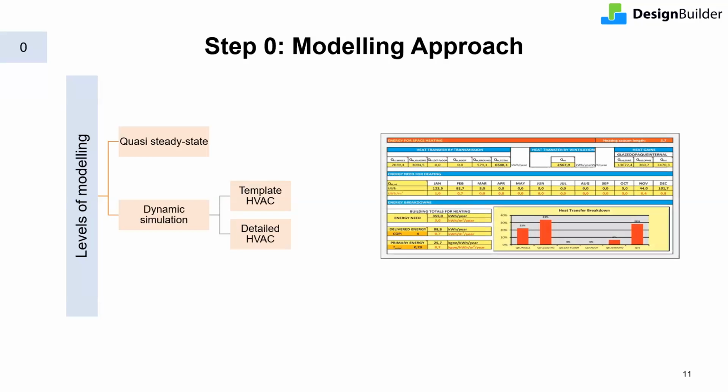Steady state modeling, such as using spreadsheets or PHPP, which is used in passive house design, although relatively simple in nature, can be very useful tools for simple projects where the heating demand drives the space loads and the variability in the building operations is less. They can be, however, less reliable for bigger projects with varying thermal loads, complex controls, and especially when cooling demand is significant.